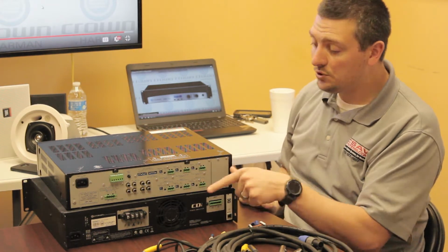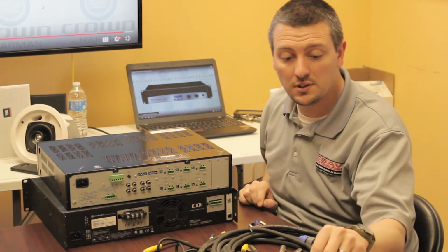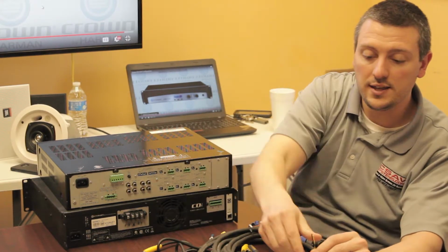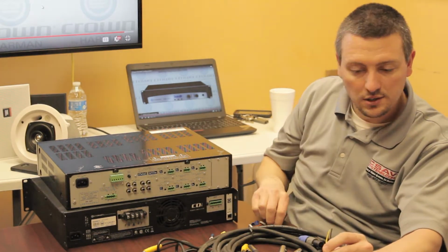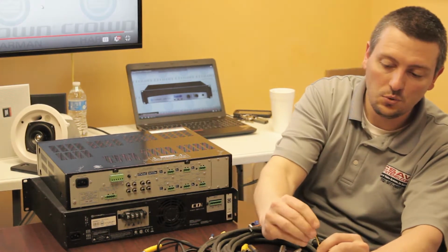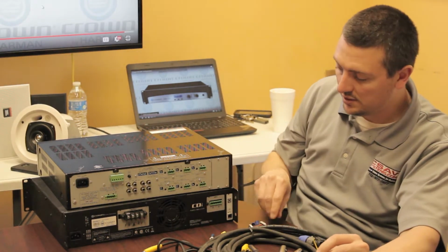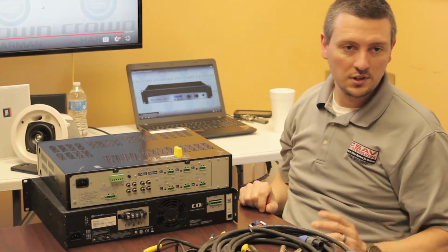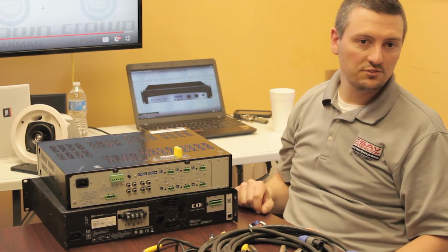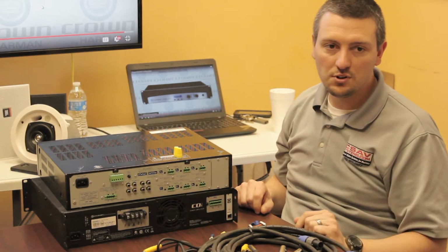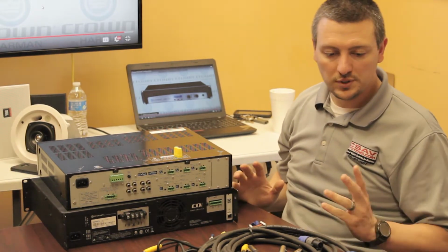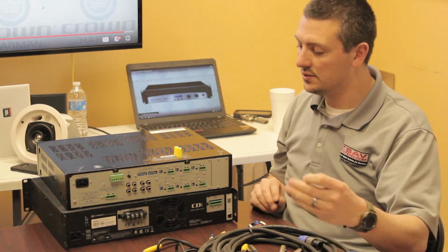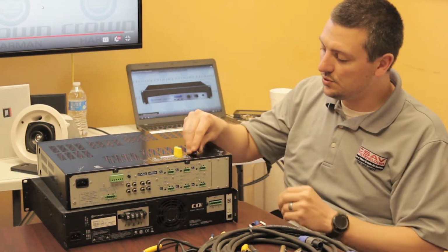If you're linking multiple speakers, anytime you're running a wire output from the volume control or the amp and doing it here, same thing. Always use wire nuts. I've had so many service calls over the years just from tape that's come off, and speakers have fallen off just because they weren't terminated the way they should have been. So anytime you're making a connection like this, always use wire nuts.